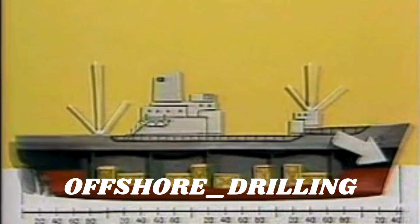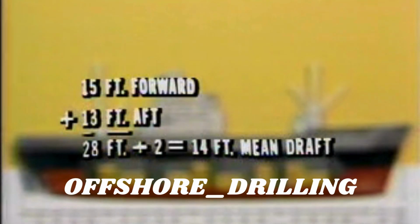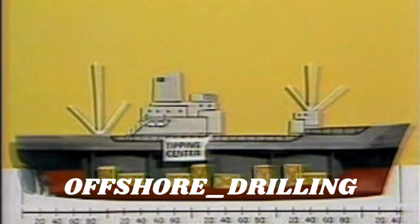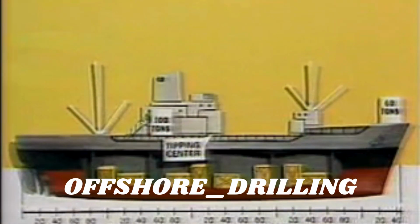Take a vessel with a forward draft of 15 feet and an after draft of 13 feet. The mean draft is an average of the two, or 14 feet. If, after examining the deadweight scale, we determine the TPI for a 14-foot mean draft to be 40 tons per inch, and if we load 60 tons 200 feet forward of the tipping center and 100 tons 50 feet aft of the tipping center, what will our final drafts be?